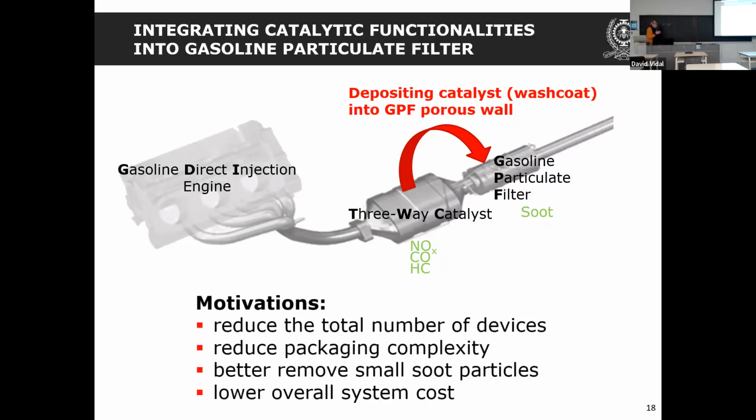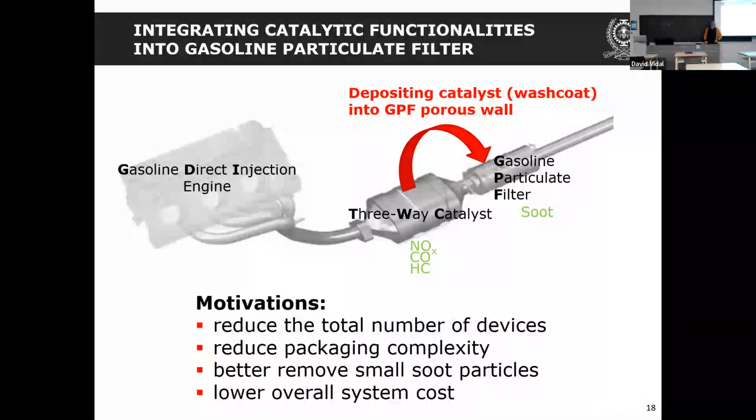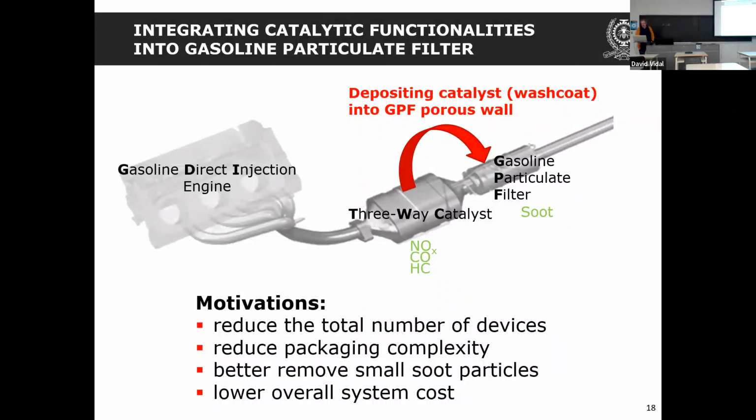The motivations are to reduce the total number of units, reduce the packaging complexity, better remove the small soot particles, and eventually lower the overall system cost. So Umicore was particularly interested in looking into the deposition of these platinum group metals into what I'm calling here a GPF, which stands for gasoline particulate filter.